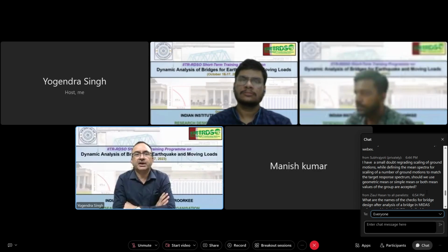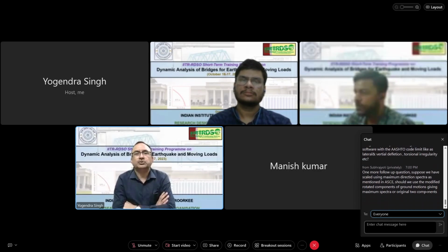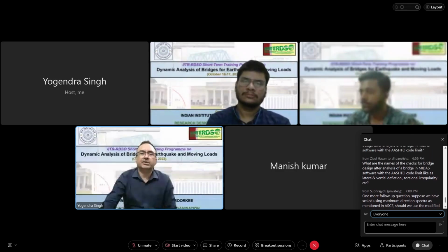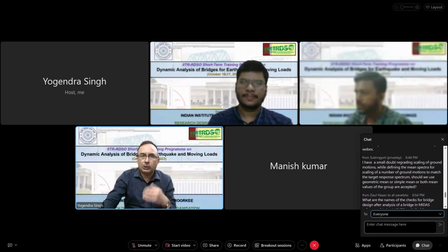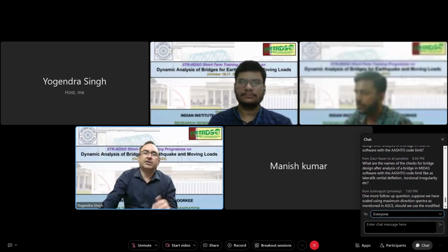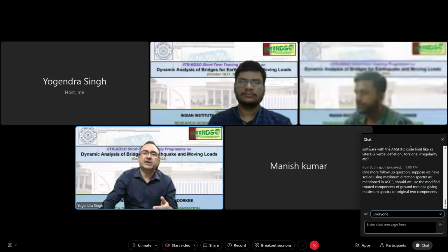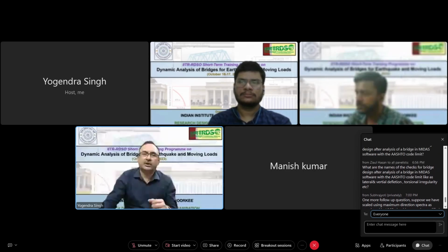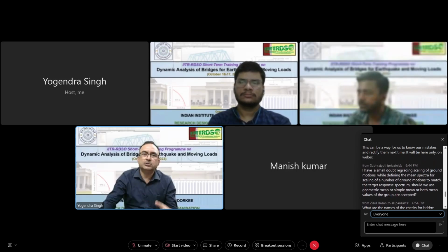We are considering the modes up to frequency of 30 hertz because the modes are arranged in the order of increasing frequency. So we will consider all those modes which are having frequency up to 30 hertz. Those modes which are having frequency more than 30 hertz are not expected to contribute much in the moving load analysis. That's why those higher modes, which are having frequency larger than 30 hertz, can be ignored.